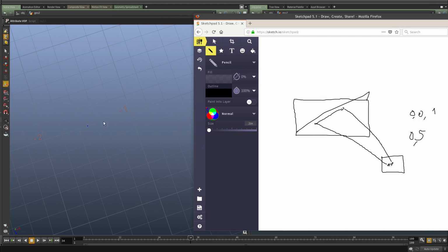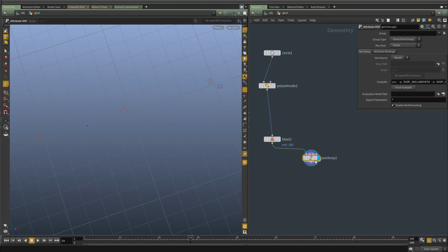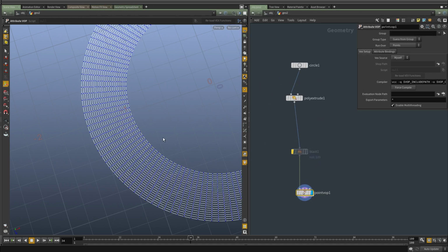And we can take this range that starts between 1 and 1.5, and instead of using that, we can tell it to go from 0 to 1. So that's what the remapping does. And with this, we can use any linear function to control the values further, because we know it starts at 0 and ends at 1. This works really well with any ramp tools in Houdini, like the float ramp and the color ramp that we're going to be using. But we're not going to do the color at this point. So I'm going to dive inside.